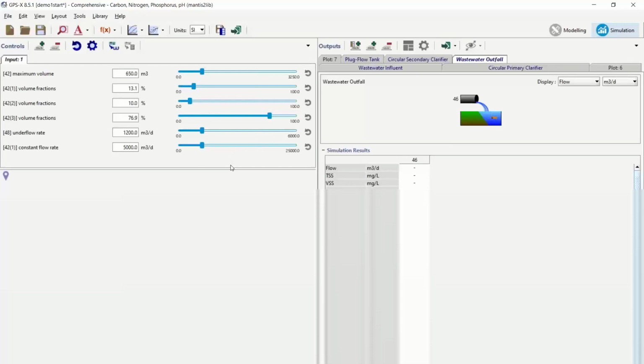So, okay, not a massive amount of change. We're still okay here, but that has improved our P, right? It was 1.1 something before, now it's 0.5. So that was a fairly good improvement. So let's see if we can also improve the denitrification here. This is 8.4 for our nitrate. So if we make this zone bigger, our anoxic zone, then that might help. So let's steal another 10% off of the aerobic zone. So now it's 20-20-60. And run that again.